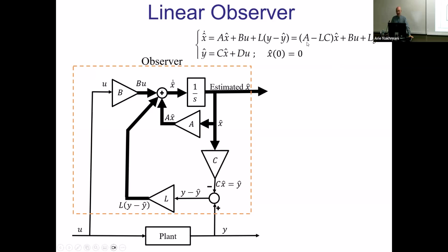And the convenient part of that is that this connects us to eigenvalues of that particular matrix. Because now these eigenvalues will tell you how fast that observer converges to the solution, which is settling time in a sense of the observer, like how fast you actually will converge to the right X. So this will give us that information about how fast you want to converge.